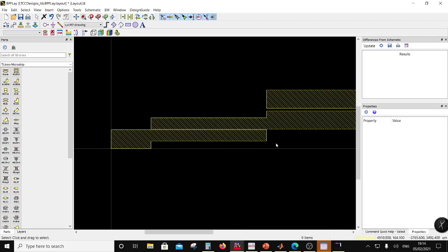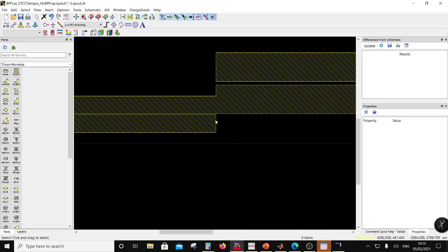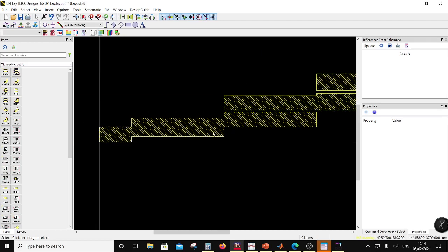Now I want to tell you that as in the case of an antenna, there is a certain width, right? And for that width there is a fringing capacitance, right? This fringing capacitance causes the length to look bigger, right? So this length is lambda by 4, and these are all lambda by 4 lengths, and this whole thing is lambda by 2. So this overlap, or this length, has to be reduced. It's usually 0.1 times the height. The height of the substrate is 379, so 37.9 or 38.